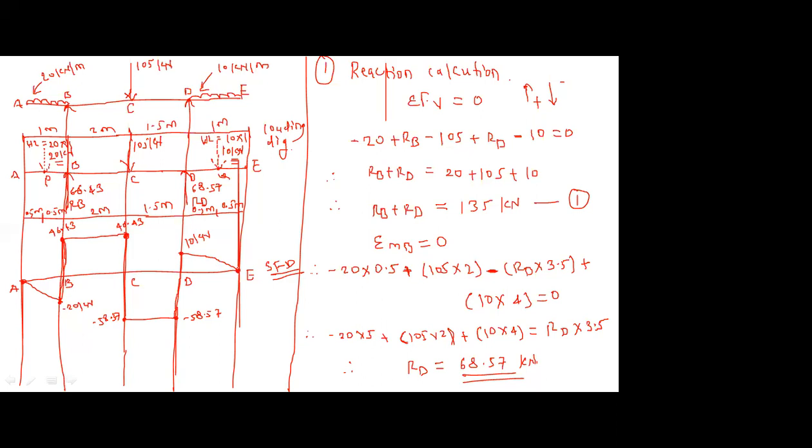So this is related to the shear force diagram for this particular overhanging beam. So if you see this particular figure, sometimes your SFD is in the positive region, sometimes in the negative region. So here you will get the point of contraflexure shear at the 3 points. Which are those? B, C, and D. Yes, which are those?